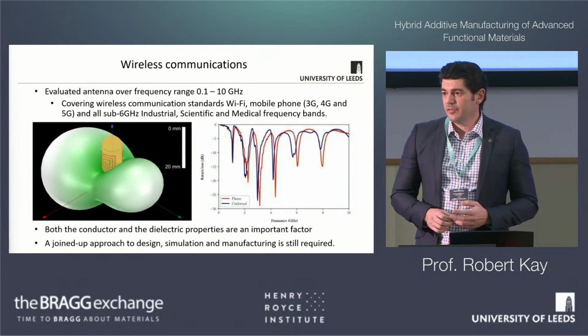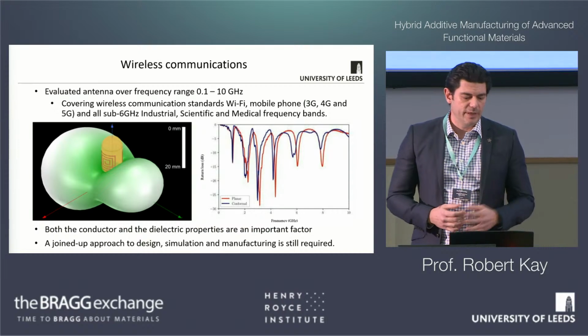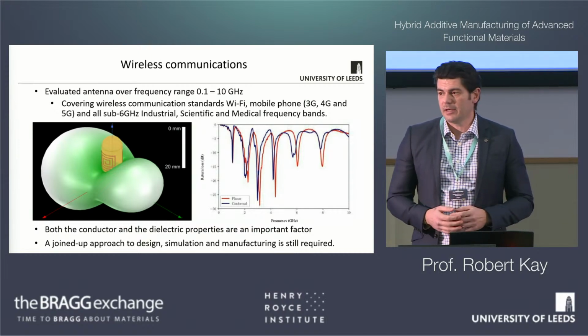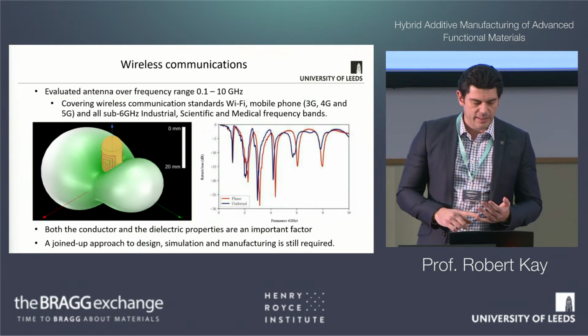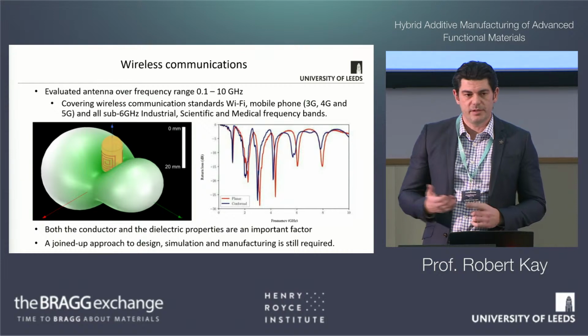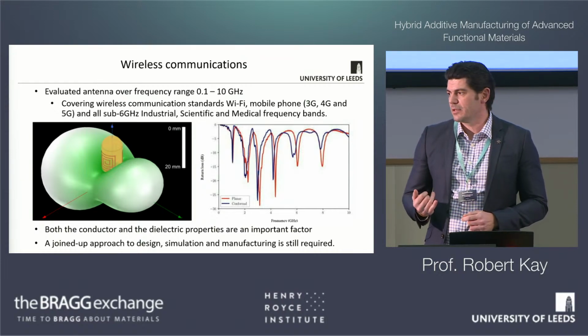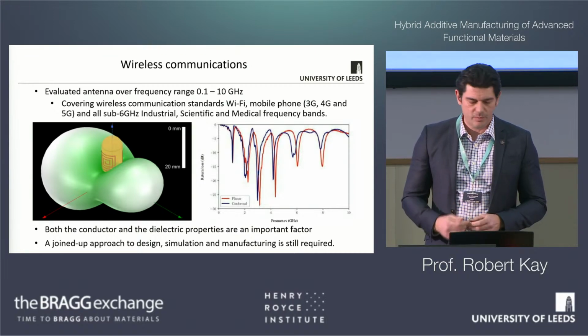And we're very pleased that there was a very good agreement between what was simulated and what we actually measured, both for the planar and for the conformal antenna. I think it's important to highlight that with 3D printing, when you get these filaments, the data sheets only go up to 1 kilohertz. So there's quite a challenge on that, and both the conductor and the dielectric properties are really important.